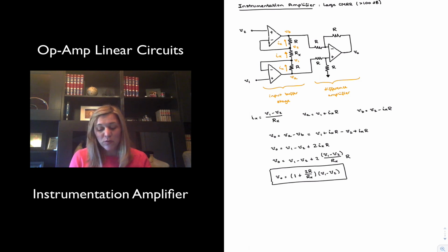There is typically one resistor that is left outside the chip to be connected externally, and that's resistor Rx. It's defined as the gain setting resistor, because the way you will set your gain, meaning the differential gain, the 1 plus 2R over Rx, that is basically the gain applied to that differential input signal, is going to be determined externally by that Rx resistor.